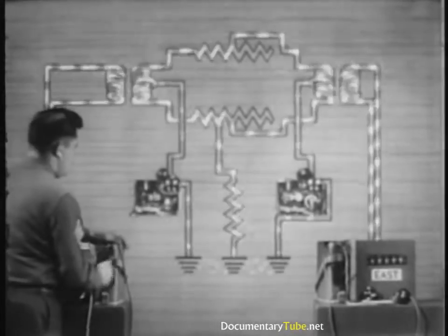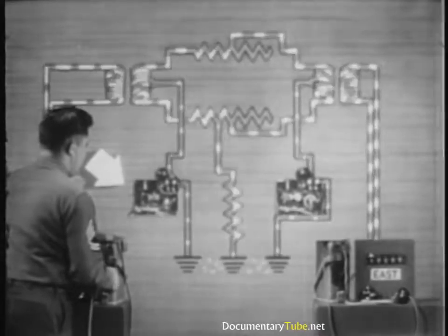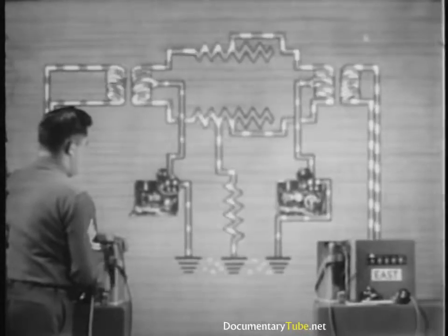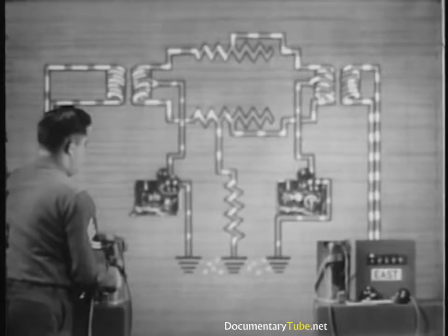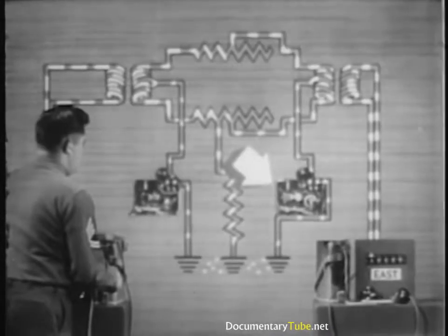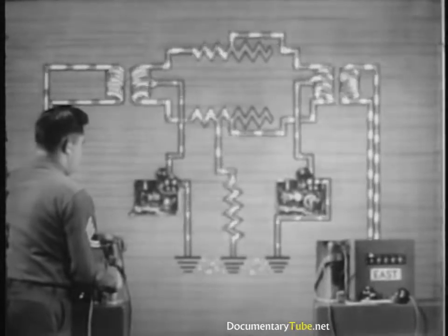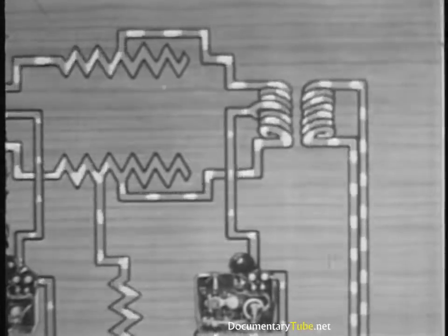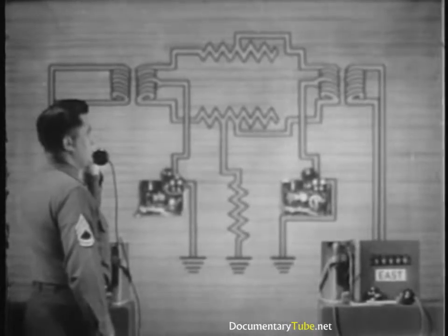When we ring on the telephone channel, some ringing current flows through the near telegraph set because the lower half of the repeating coil has a shortened path through the accidental ground. This causes an unbalance in the normal ringing path, so that a small amount flows through the far telegraph set too. Because of this, the ringing current delivered to the far switchboard is less than normal. Voice current, however, is unaffected.